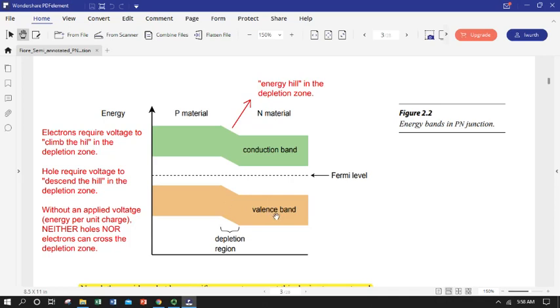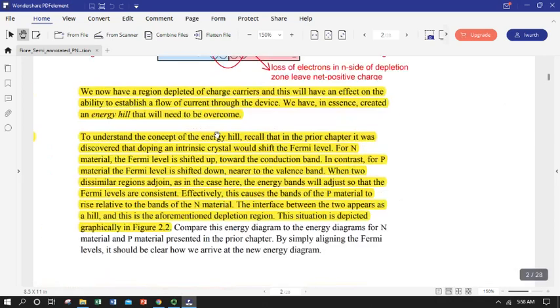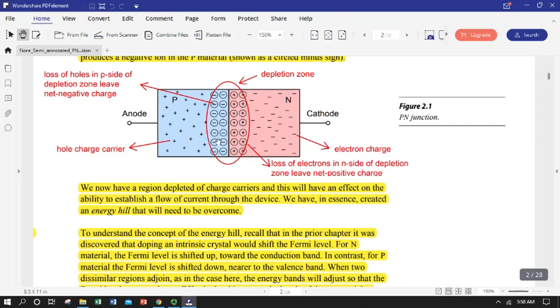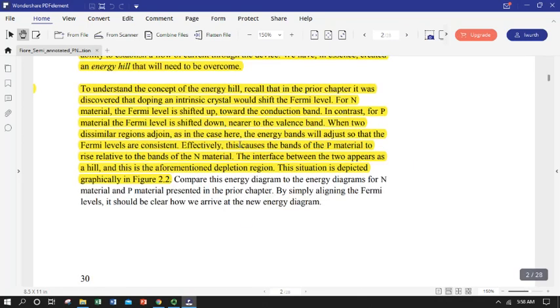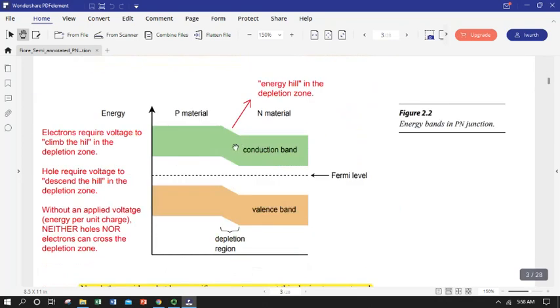So we've got to provide energy for both flavors of charge carriers. This is one of the features of a PN junction. It doesn't have a lot of charge carriers right within itself, but more importantly, the action of this fixed charge at the interface changes the position of our energy bands, and it creates a voltage gradient. This is another way of looking at that fixed voltage of the interface.